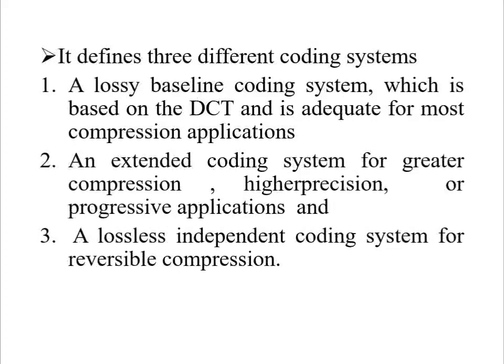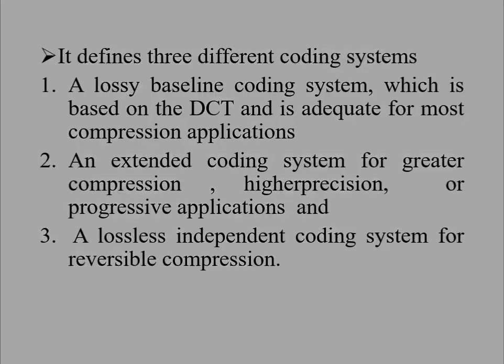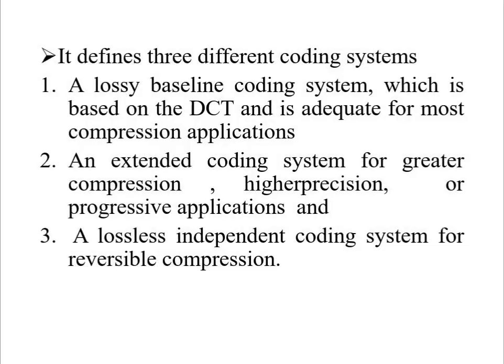The figure, from A through F, shows six threshold-coded approximations of the monochrome image. In figure A, all images were generated using an 8x8 DCT and normalization array. The first result, which provided a compression ratio of about 12:1, was obtained by direct application of that normalization array.